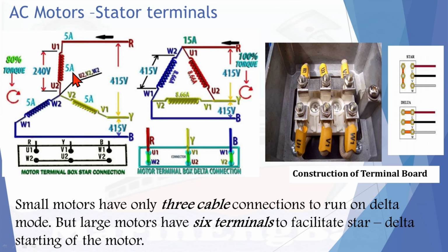Once the motor has started, obviously it will create low torque, because the voltage and current both are less. So the power will ultimately be less. Even so, you will have less current for starting. So that is good for your cabling and other protection. Your other systems will not get interrupted by the power surge and these things.